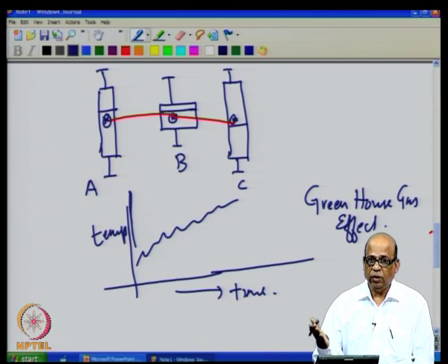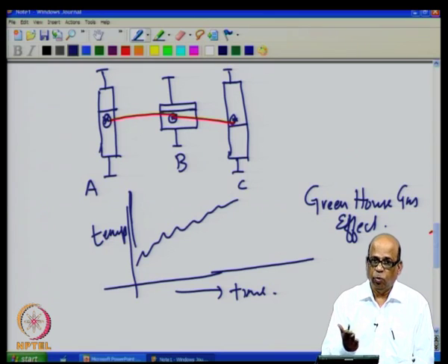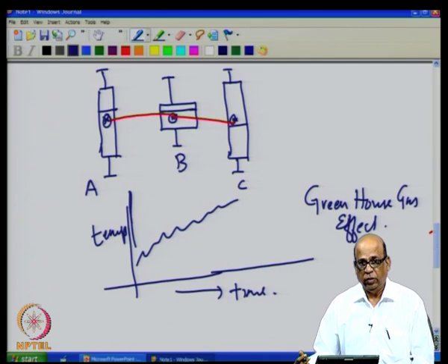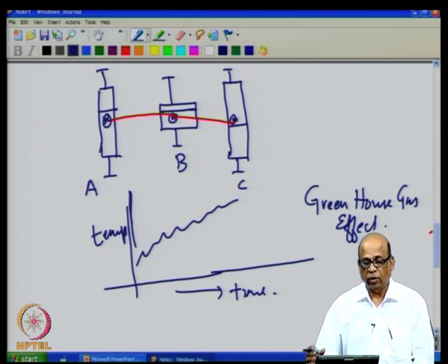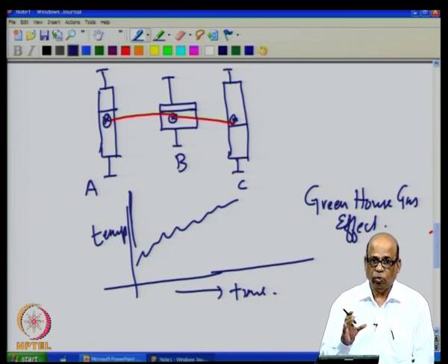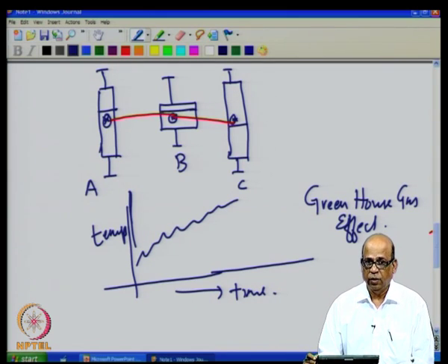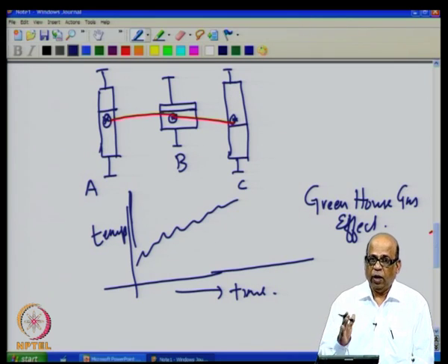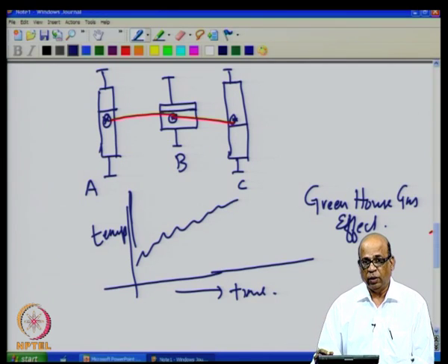The sea level increase will have implications on the saltwater intrusion into the lands, apart from having implications on coastal inundation. That is, the sea levels will start ingressing into the mainlands, and therefore coastal inundation is possible. The precipitation patterns changing will have implications on flooding. There may be high intensity, short duration rainfalls increasing, and therefore it will have implications on flooding. Also, it may have implications on droughts and on water availability, because precipitation will contribute to water availability.